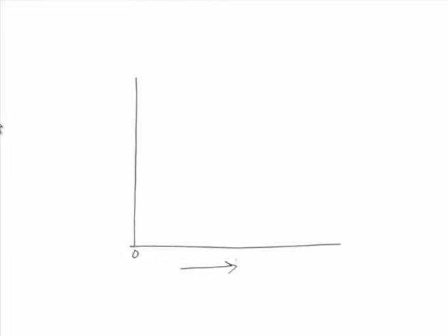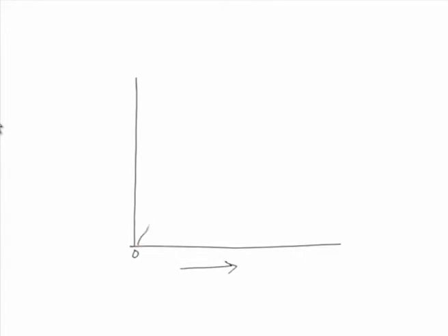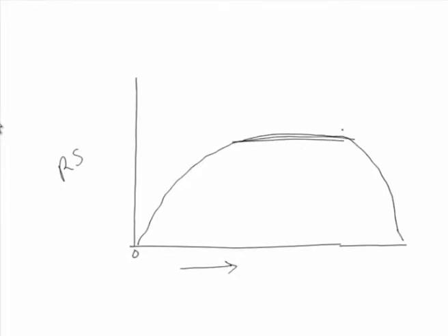With the increase in distance from one side to the other along the weld center line, the magnitude of the residual stress increases gradually, becomes maximum, and then tends to become zero again. This is one end, and this is the other end of the weld. So, the residual stress magnitude will be maximum about the center of the weld, and this is the length